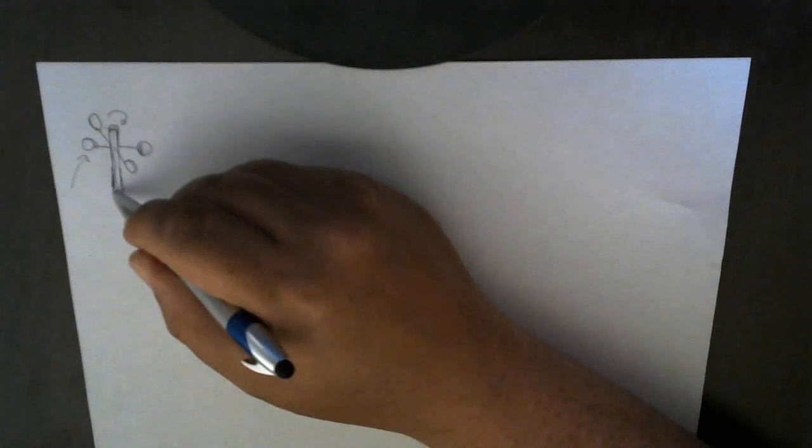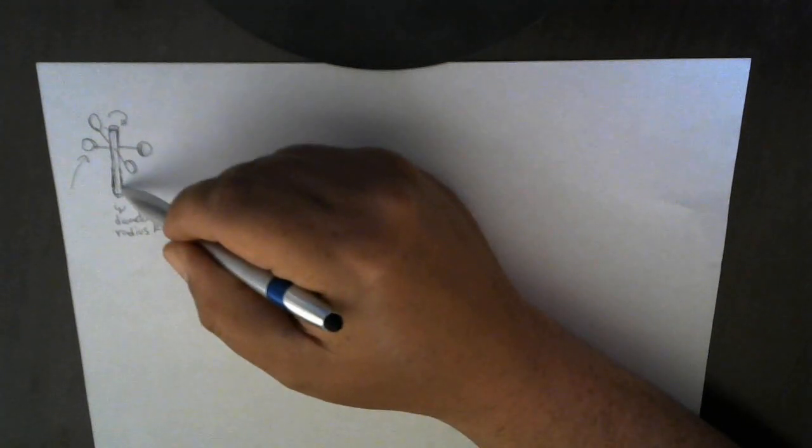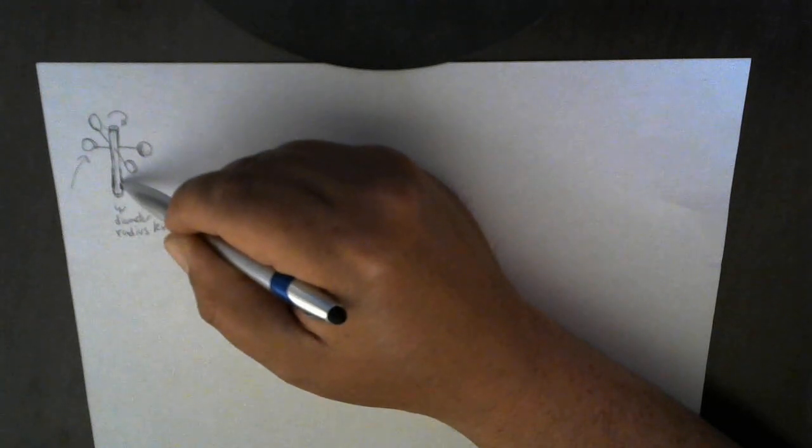And so the way we can design it is we know the fixed diameter of the shaft. So let's say we use PVC pipe like I have at home. We know the diameter, therefore we know the radius. Then what we do is we mount a magnet to the shaft. The magnet's going to be tiny.